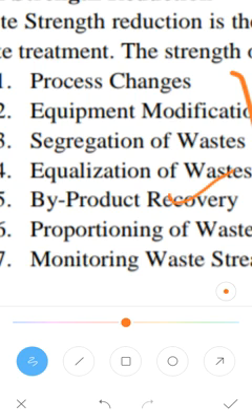In byproduct recovery, all the valuable material contained in the process waste has to be recovered, and the rest of the water is available for treating. Next is the proportioning of the waste. Proportioning the discharge of concentrated waste to the sewers and plants reduces the strength, so that the total waste can be removed in the minimal final treatment process, which causes the least damage to the streams.